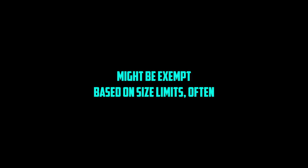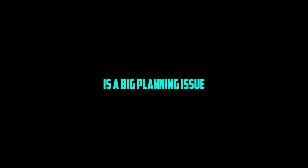Planning permission again. Some things don't need it. Small extensions, permitted development, might be exempt based on size limits, often related back to the house's original 1948 volume. Bizarrely, small porches too. But you always need specific consent for work on listed buildings or demolition in a conservation area. And dealing with contaminated sites is a big planning issue now, too.